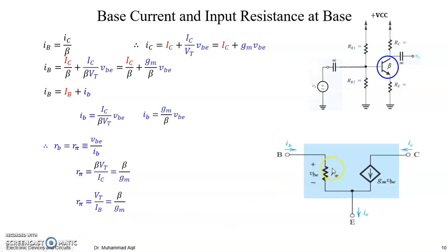So this resistance at which this base to emitter voltage will be developed out of this input voltage, because out of this input voltage some part of this will be VBE, and how much it would be, the value of this resistor will define. If this resistance is large, this will take more contribution from this input, and it can then be multiplied with gm to have more current. So it means it's totally depending on your biasing as well, right?